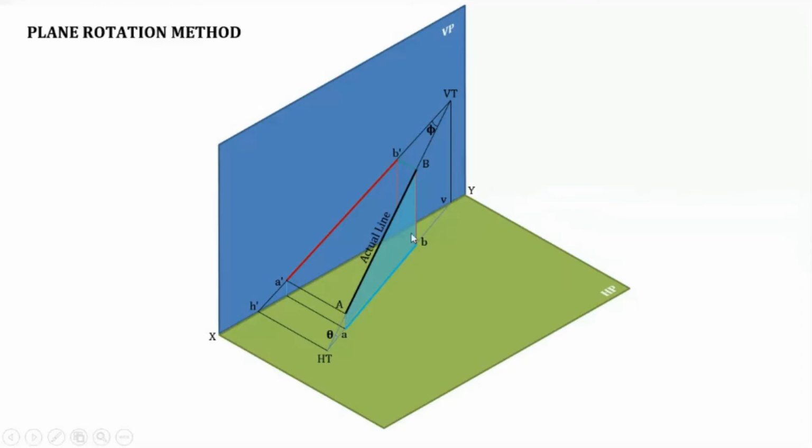These are perpendicular to the HP. Any line which is perpendicular to the HP should be parallel to any other such perpendicular. So this line AB, BB as well as BA, AA, capital A, small a, capital B, small b, these two sides are parallel, but capital AB as well as small letter ab, these two are not parallel lines. So this is a trapezium, a plane. This is the trapezium that we consider, or this is the plane which we rotate.